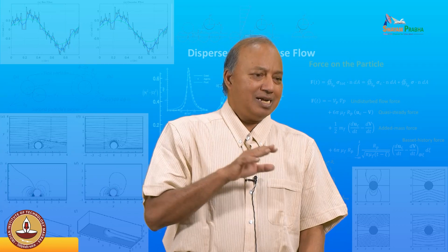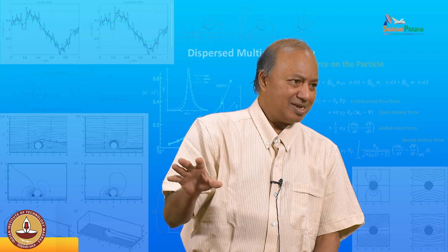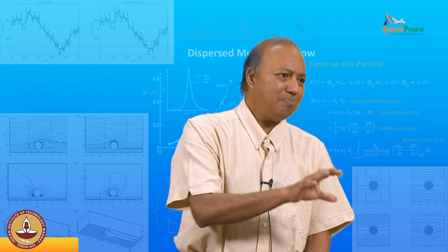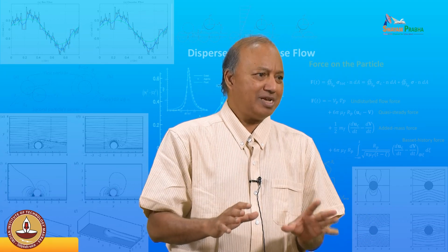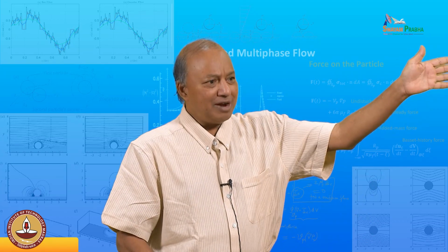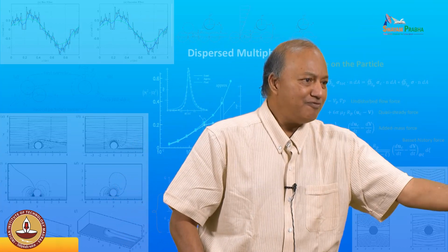In a one-way coupling, no problem at all. In two-way coupled simulations, be careful what the feedback is. The easiest way is, after you calculate feedback, you plot your advection term, you plot your diffusion term over your entire domain, you plot your feedback term, and see how they look, what their values are. Because if you finally got a gibberish-looking flow, you have to go back and debug and ask who caused it. Especially if you wrote your own code, it could be a bug.